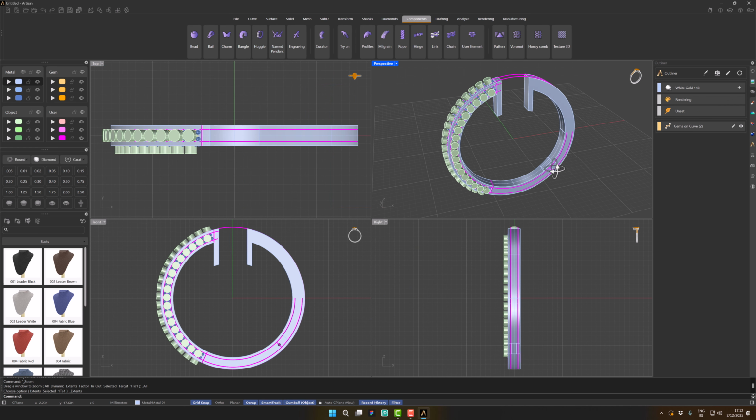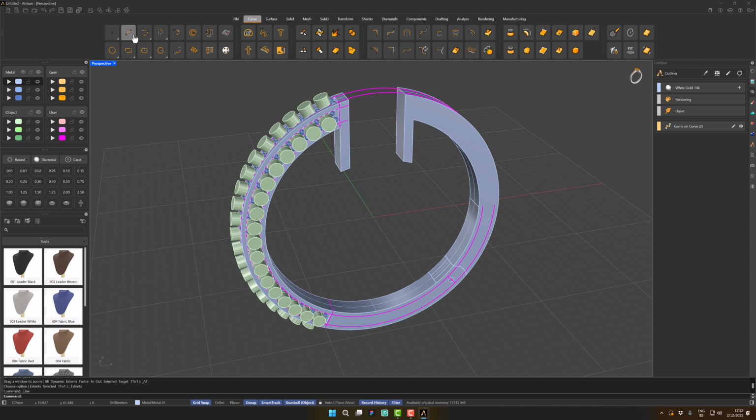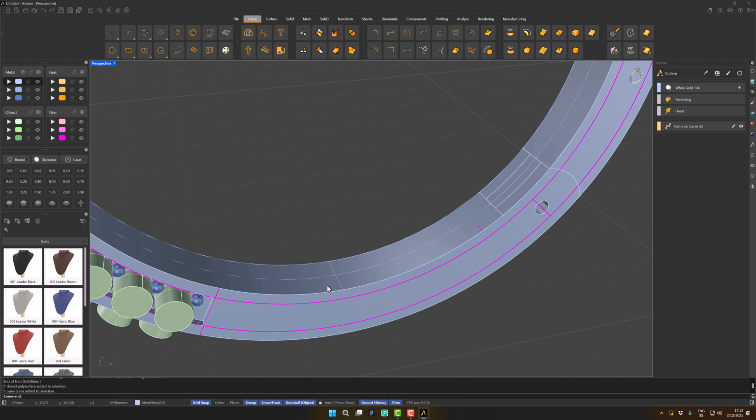Let's create the final reference curves for the last channels. Since we want the hinge axis to be solid, draw lines to keep the channels away from the hinge for added strength. Draw a line leaving a margin near the axis. Now select the projected curve on the left side and click Explode. Delete the inner curve to avoid conflicts with Push and Pull.